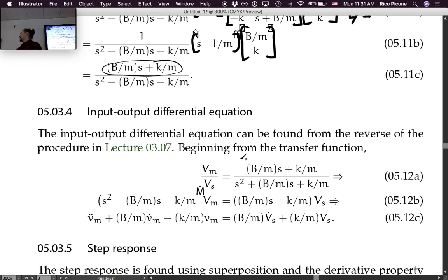In this little bit here, we're going to go from the transfer function to the differential equation, which is essentially the same exact procedure, but we take the inverse Laplace transform. But really, it's just like by inspection, because we don't really get into the details of the inverse Laplace transform, because all we care about is the derivative term Laplace transform, which is always just s to whatever power is the derivative to that power, that order of derivative.